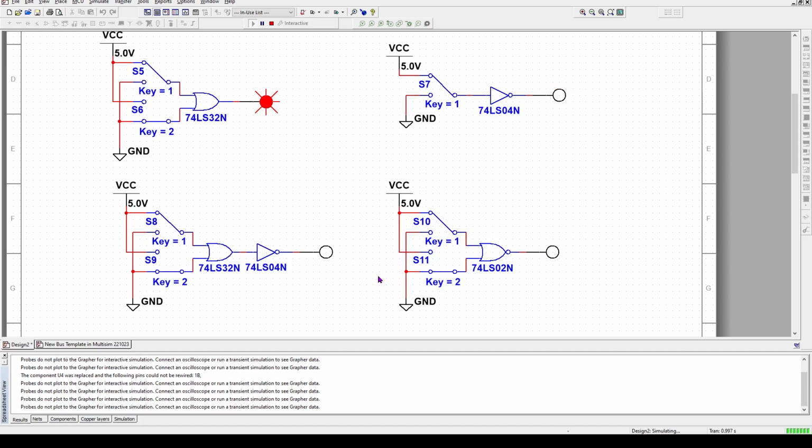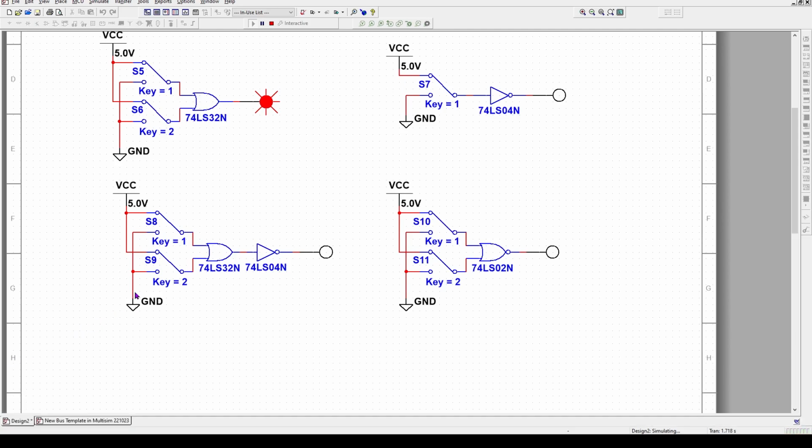This is a binary 2. 1, 0. Well, 1 plus 0 is 1. And it's inverted to be a 0. And the last one, this is 1 plus 1. True plus true is a true, so it should be a 1 here, which is flipped over to be a false here. And the NOR gate is actually following along and doing the same thing. So here is a NOR gate with an expanded NOT and OR gate, and this is the NOR gate itself.